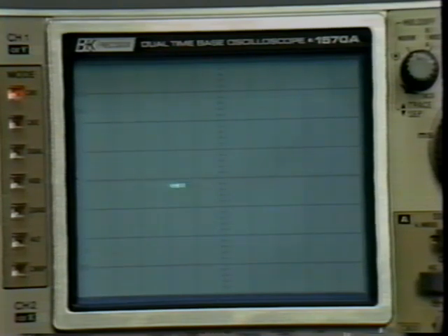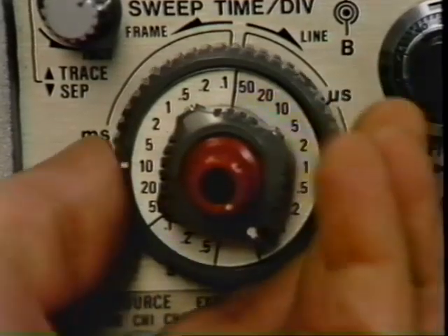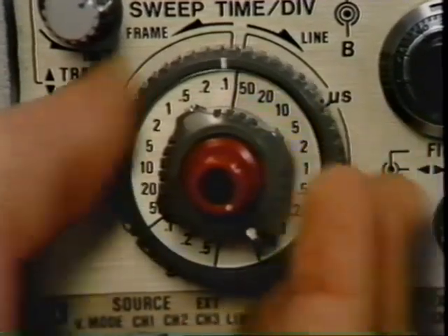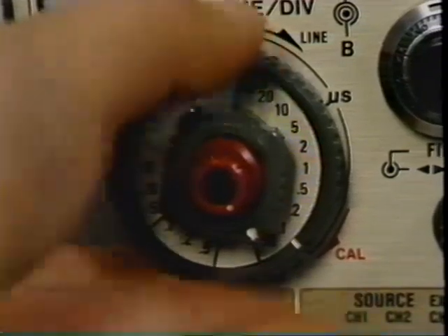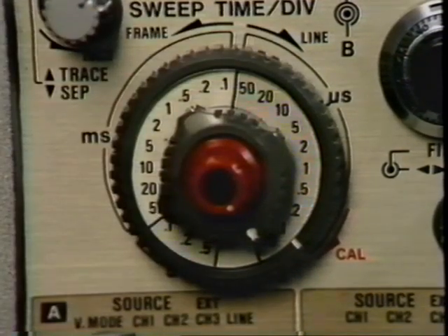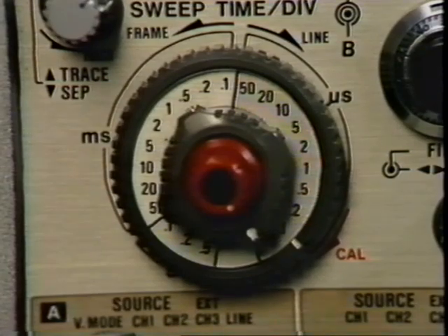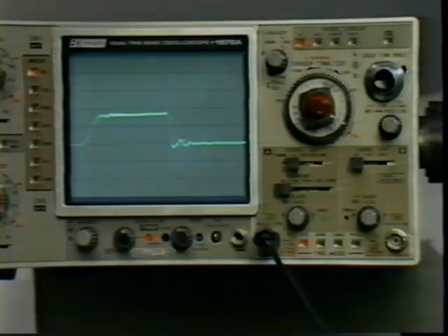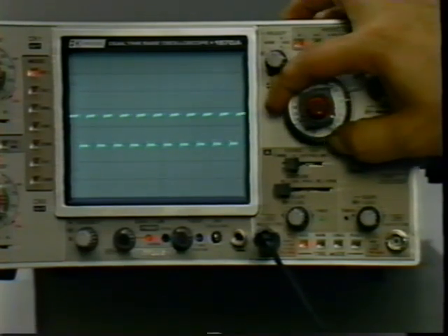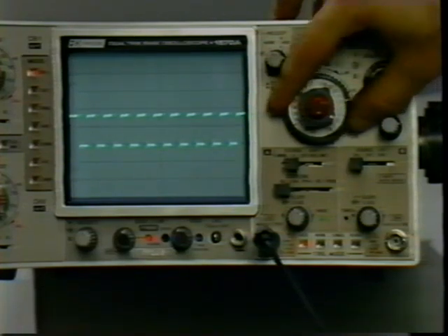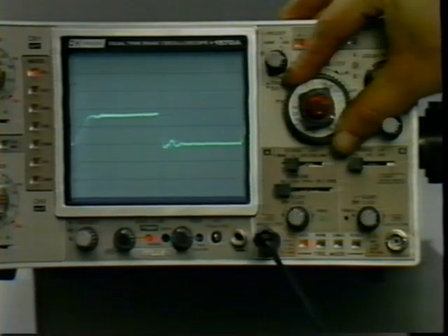to represent voltage. To see a greater or smaller section of the waveform, we vary the speed of the sawtooth sweep signal by setting the time base or time per division switch. The higher the time base setting, the faster the sweep. Increasing the sweep speed will show a smaller portion of the input signal, and decreasing it will display more repetitions of the wave. A variable control on the time base selector can slow the speed of the sweep.